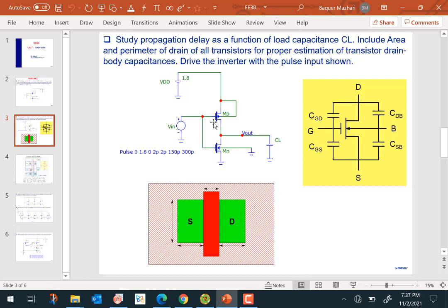Now this is the schematic of a MOSFET. This is a simplified layout of a MOSFET. The green ones are the N plus source and N plus drain, and this is where we have polysilicon and the gate. When we talk about the drain to body capacitance, we are talking about the capacitance coming about because of this drain region. Note that drain is N plus, and underneath the drain there is the body, which is p-type. So there is a p-n junction kind of capacitance here.